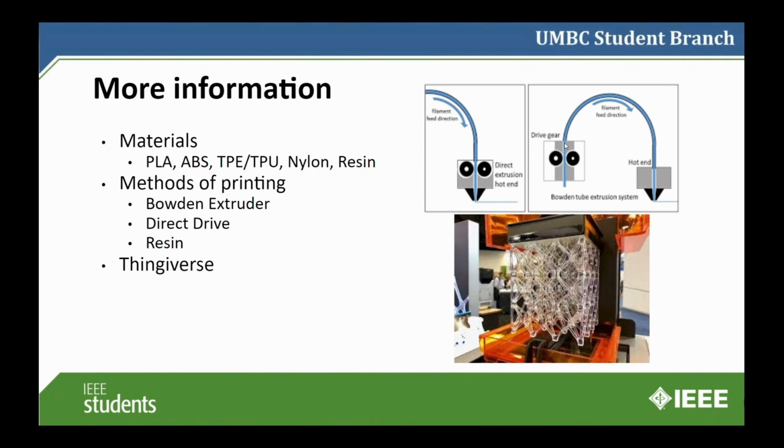As it's pushing the filament through that plastic tube, your hot end or your extruder or your metal tip has to be hot enough to ensure that it can melt the plastic. And the reason why your extruder kind of looks like a triangle is that it sets the filament width, or the diameter of how much filament comes out of that printer. And so that's that quote unquote Bowden type tube.